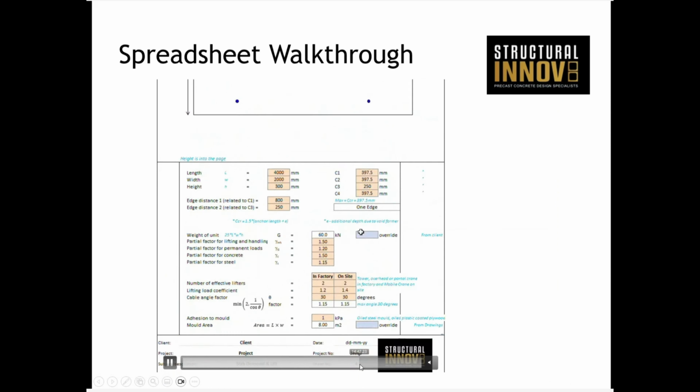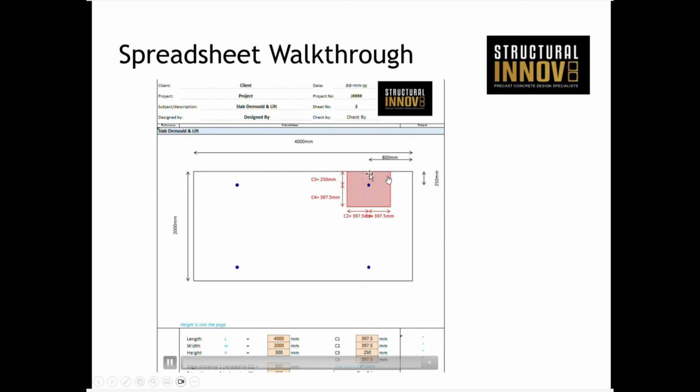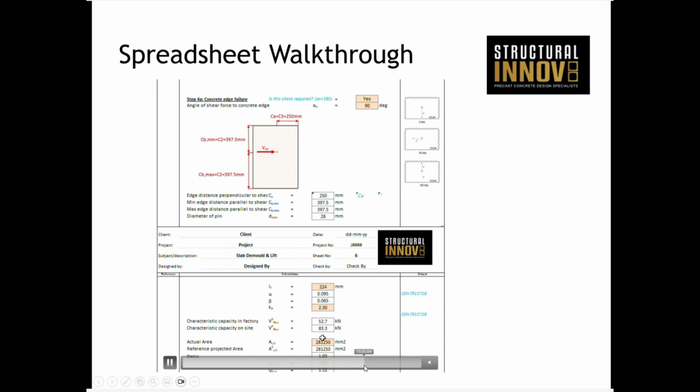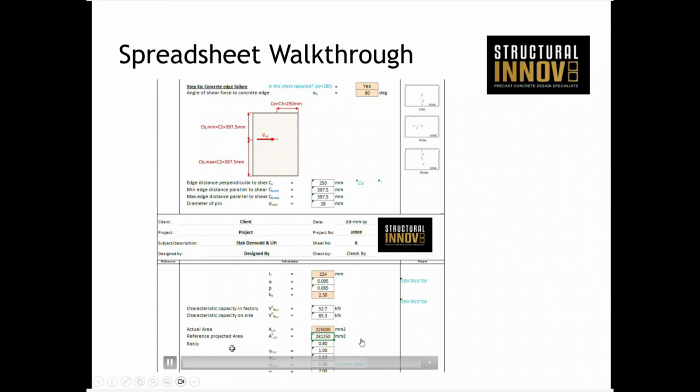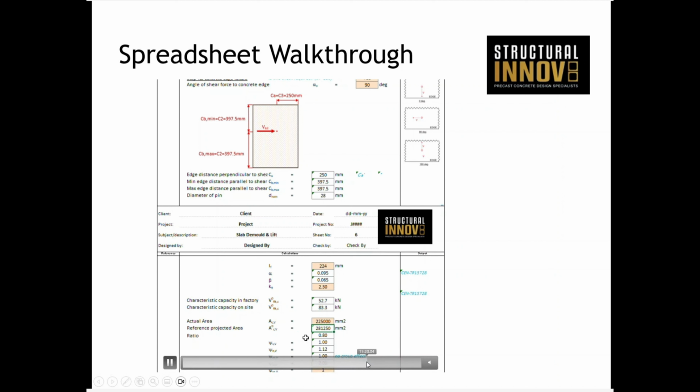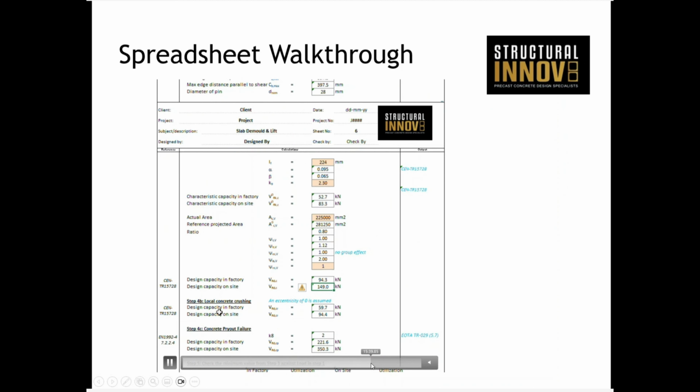So we have to the left, we have to the right, and in the thickness, as we stated there, in the height dimension there is 300. So we just work out that, and we put in a 225 in there, and that'll give us the reduction factor. So that's gone to 0.8 reduction factor for that. So again, it's just logical flow, following through the whole thing.